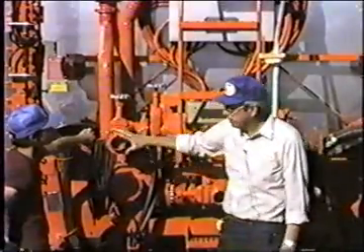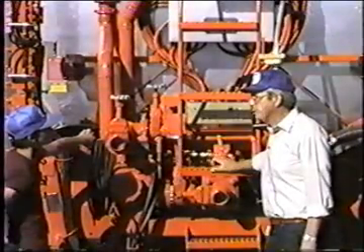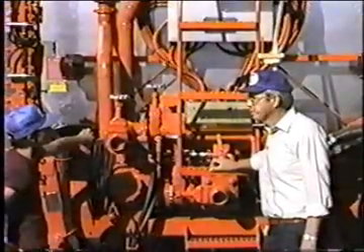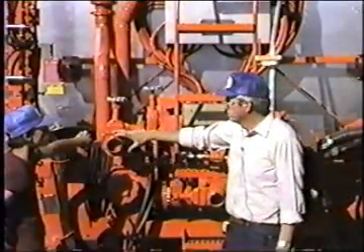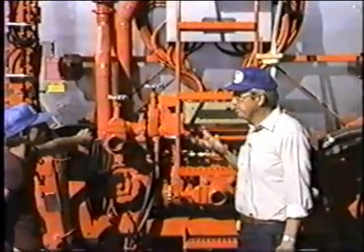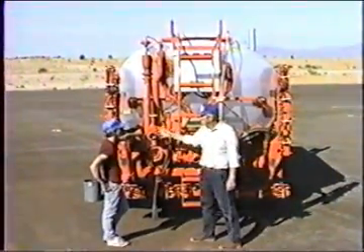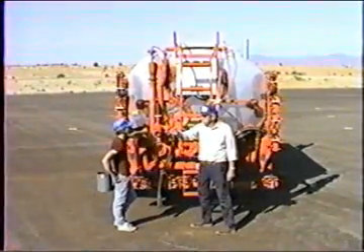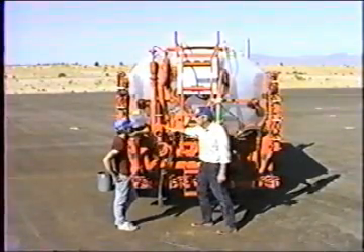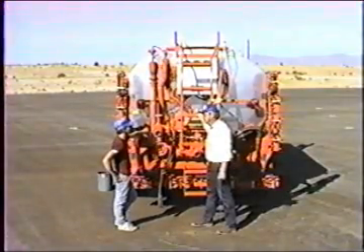If we had 4-inch here and 4-inch hoses, and a few people do that just for speed, if we had 4-inch hose, 4-inch piping, and we had good clean 4-inch valves on the transport, then we can pull 400 gallons a minute. The only thing that's causing material to go through this hose is atmospheric pressure, which at this altitude is about 15 psi, and gravity, and that adds another couple of psi. So maybe at the very most we've got 17 pounds per square inch pushing the asphalt through that hose into here. Once it gets into the pump, then we've got a 200 horsepower diesel engine up front that's pushing it.